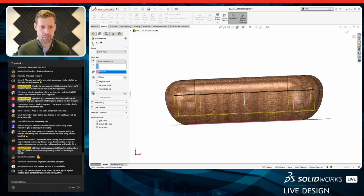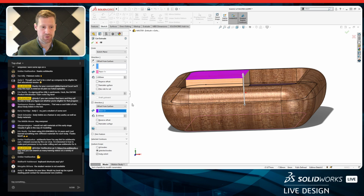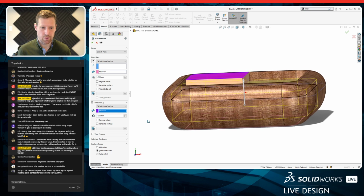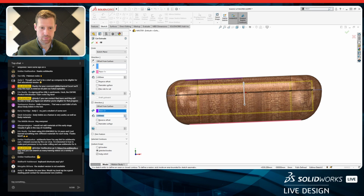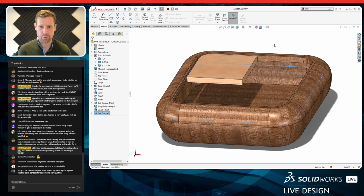But I don't want to hit check now. I want to actually extrude it in the other direction too. So let's go to direction 2, and we're going to do the same thing. I don't want to just blindly extrude it. I want to go to offset from surface, select my top surface here, and then we'll minimize that to whatever we think is appropriate. Maybe, yeah, 2 millimeters looks good here. So we'll hit check to confirm, and now those have come out.